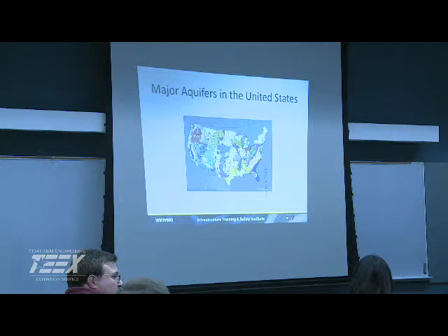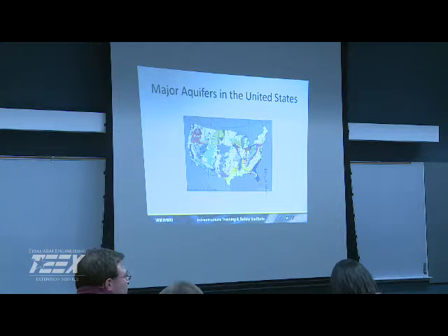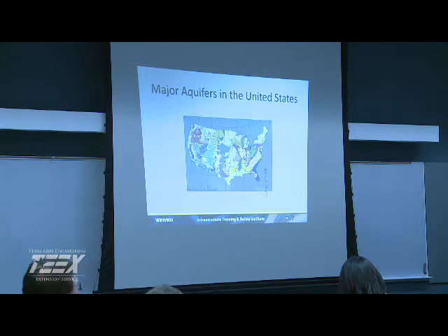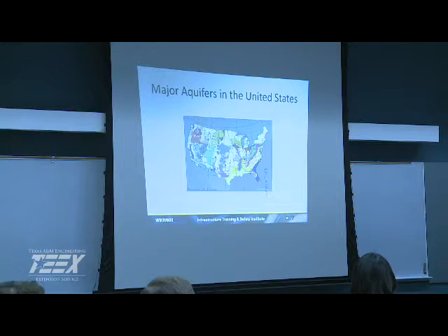Surface water. I'd actually say the number of systems is probably pretty equal, groundwater to surface water, but then when you get into capacity, volumes, most of the groundwater systems are smaller systems, and most of our larger systems utilize surface water. So percentage of water use, I'd say probably 80 or 90% is surface. Well, see, you might have a lot of water there, but you might not be able to get it out easy. The transmissivity of your aquifers and stuff like that, how easy the water flows.